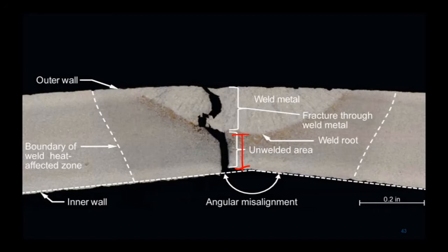The flaw was big enough to be detected, not by a corrosion inline inspection tool, but it could have been detected and measured by a transversal circumferential magnetic MFL tool, probably by an ultrasonic inline inspection tool or an EMAT tool. But the pipeline had never been inspected with an inline inspection tool. The failure is almost 50% of the wall thickness, in the area that was not welded.